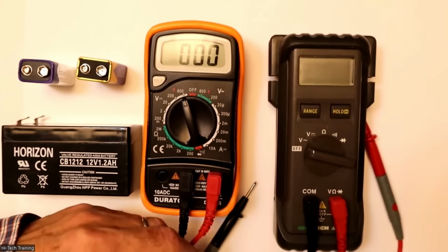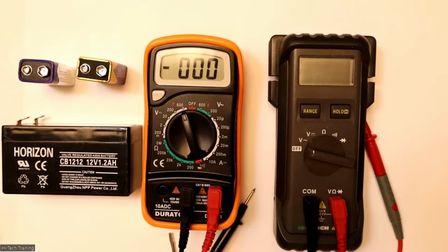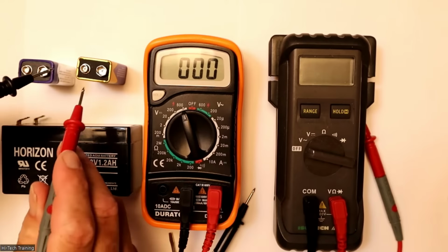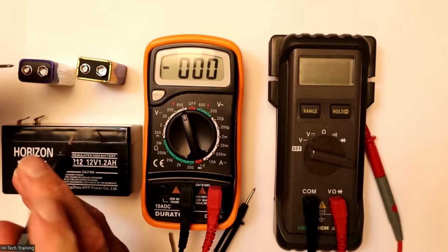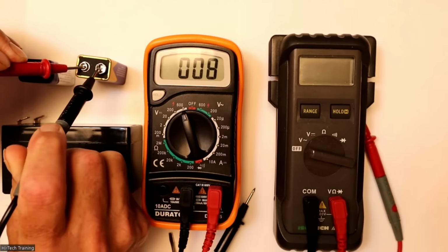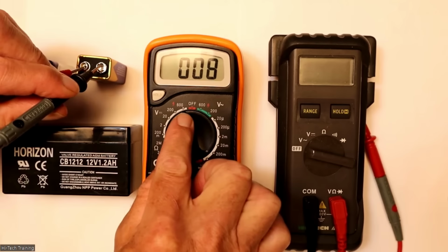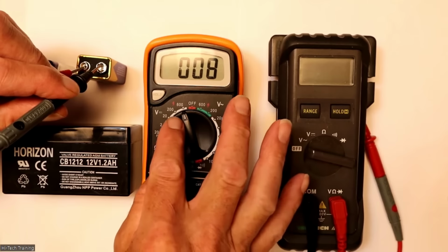So we'll just get our probes again from this meter and go on here to read our volts on it. So here's the plus, this is the minus. Yes, so plus minus. Let's see what we get. So come on here, we're getting 8 volts. Okay, so 8 volts, it's supposed to be 9 volts, but I'm on the high range here. So if it's around 8 volts, I can actually go on the lower range.